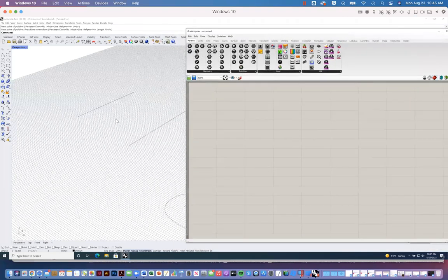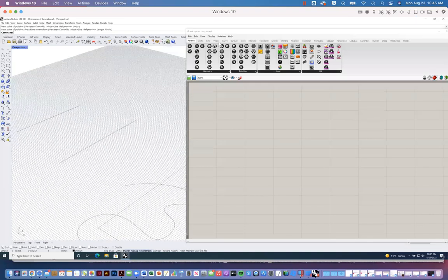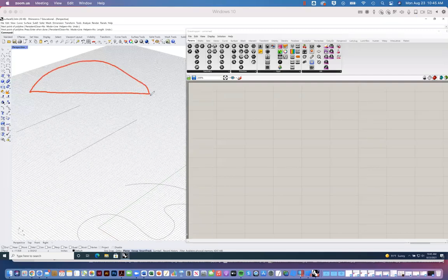So what I'm going to do is I'm going to build a truss, right? We all know what trusses are. I hope so. You want to be an architect, it sure helps if you know what a truss is. So let me just demonstrate what a bow truss is. I'm going to have a bottom string and a top string, and the top string is going to look like an arc, right? So this looks almost like a bow from a bow and arrow. The top chord is curved, the bottom chord is straight, and I'm going to add this diagonal webbing in between, right?